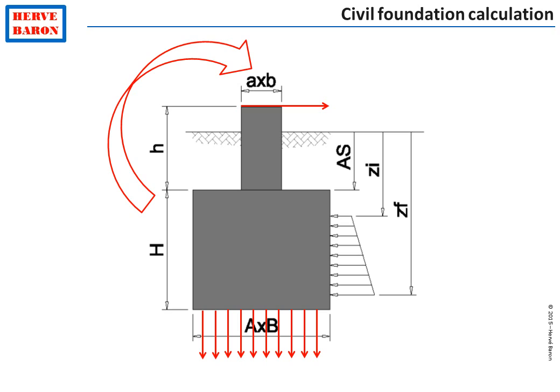The foundation size is determined in order not to exceed the maximum soil bearing pressure, and so that the equipment will not slide and will not turn over.